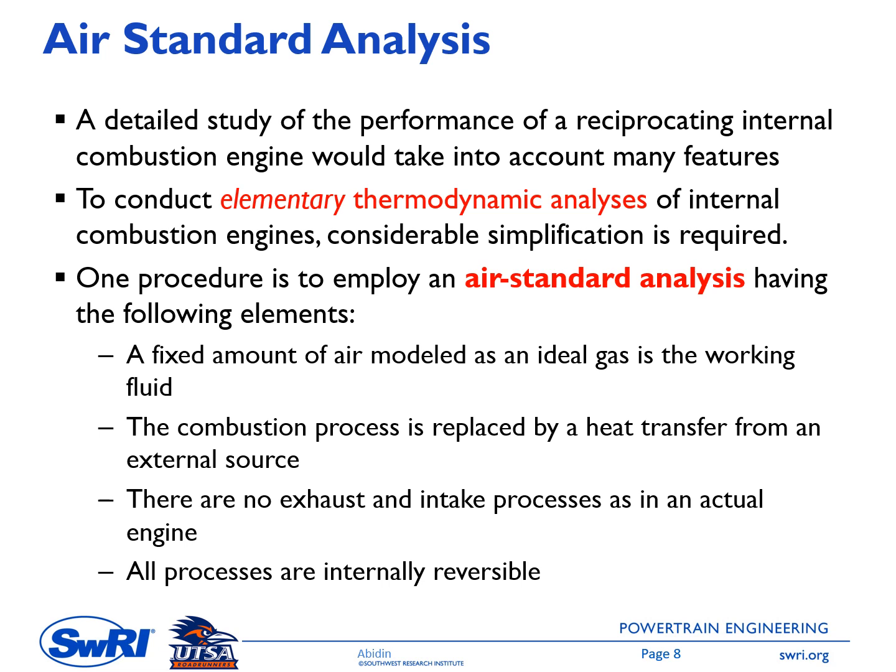So in this air standard analysis, a fixed amount of air modeled as an ideal gas is the working fluid. We will ignore the fuel, or we do have the fuel, but we assume the fuel properties are the same as the air properties, so that the whole mixture composition is 100% air. And then the combustion process is replaced by a heat transfer from an external source. So no combustion process at all in this analysis.